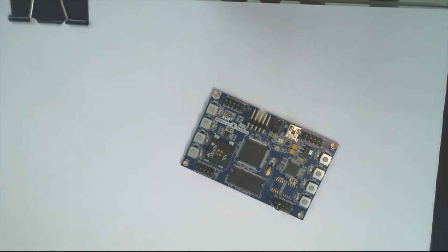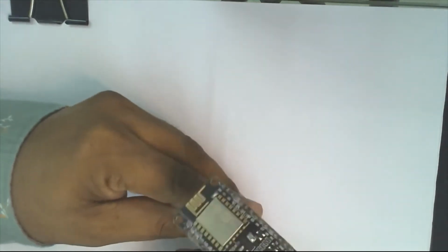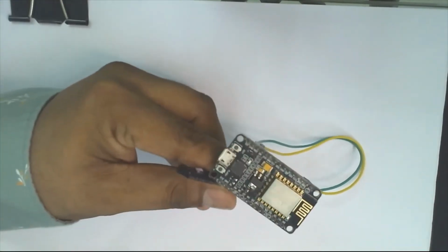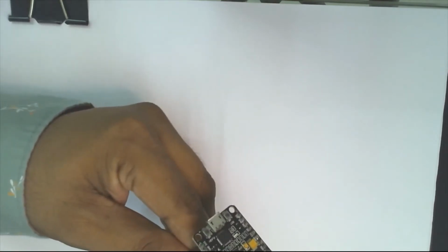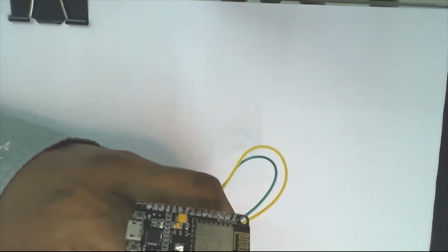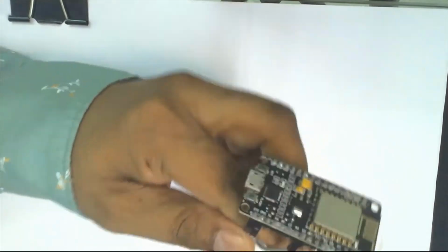And embedded systems, if it depends on a network for the resources, then the system is called a network embedded system. For example, embedded systems developed using ESP8266. Now this embedded system needs a Wi-Fi connection to provide an output. Let's say I have developed a temperature data logger using this, and this temperature data logger sends output to a particular server. So I have at home several such temperature data loggers along with humidity data loggers. I have used IoT server along with display board and database. In the background, I have used InfluxDB database along with Grafana for displaying the details. So these are nothing but the server requirement, and this device needs a server for its working, and that's why we can call such an embedded system a network embedded system.